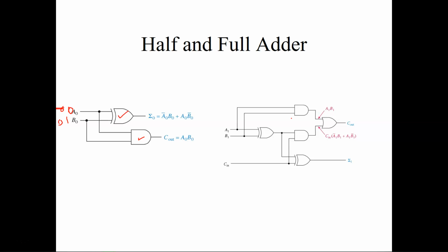All right, so looking at this guy, you're again looking at different ways that these guys are being used. This one is again tied to the AND gate. It's tied to an exclusive OR gate. And the outputs for the AND go to an OR gate. The output for the exclusive OR gate goes to an AND gate and another exclusive OR gate. So what does that mean for our signal? If I have a 1 and a 0 at A and B, that means I'm not going to get a signal through this guy. You can just forget him, right?